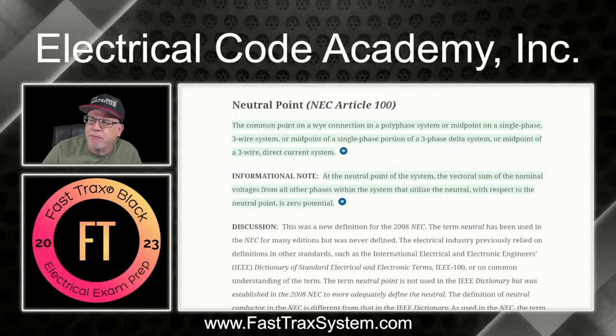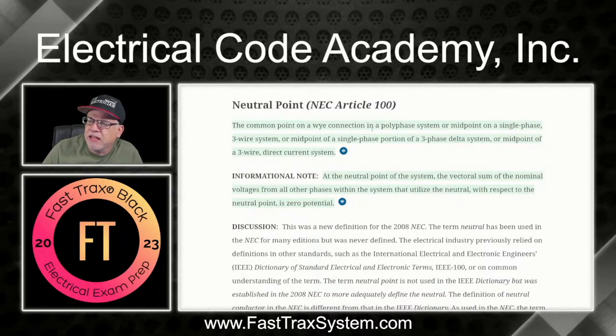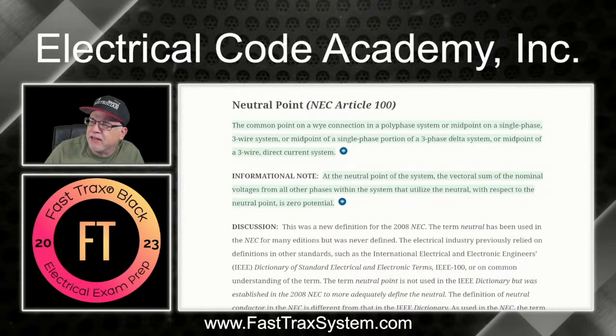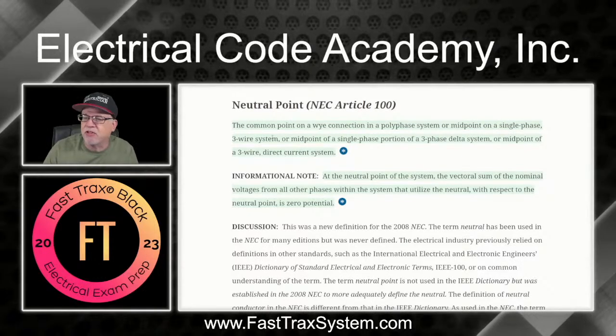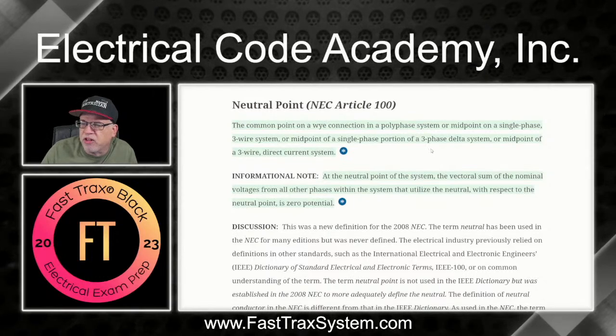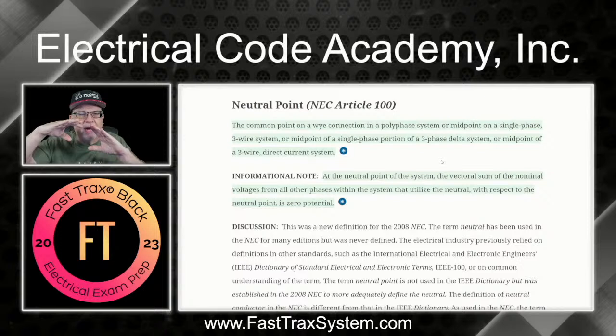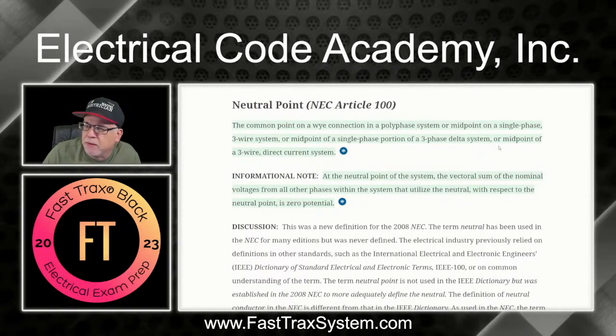It says a common point on a Y connection in a polyphase system, and that's that midpoint. We'll look at a graphic here in a second. Or the midpoint on a single phase 3-wire system. So again, that 120/240 volt on a winding, that midpoint connection, okay, that creates a neutral. Or the midpoint on a single phase portion of a 3-phase delta. So you have A, B, and C delta, and you're just taking one winding, and it's the midpoint of one winding, okay, creating a midpoint, neutral point. And of course, it also talks about the midpoint of a 3-wire direct current DC system.